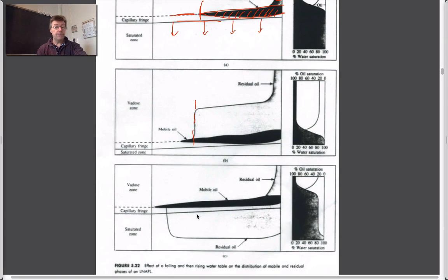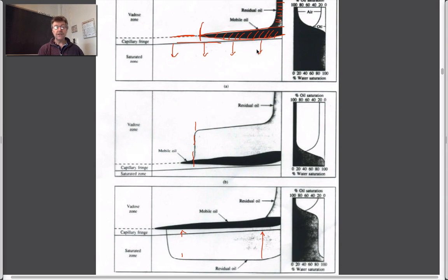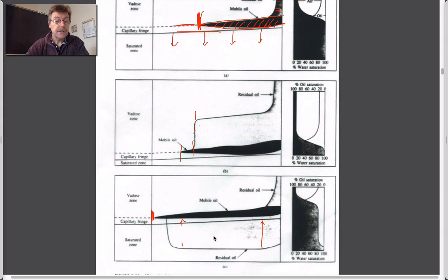It rains again in the fall, and the water table rises, and it retreats back up here to its previous condition. So there's really no difference between this stage and this stage except for two things. One is that you've smeared this zone underneath, which didn't exist before. And secondly, because you're jiggling around with this stuff, instead of the lateral extent of this lens being over here, now it's gone a bit further and a little bit further just because it's being messed around, it's been moved up and down. And so it's a way that it can spread laterally and also be present below the groundwater table, even though it shouldn't really get there. But the mechanism it got there is just by a rise and fall now.